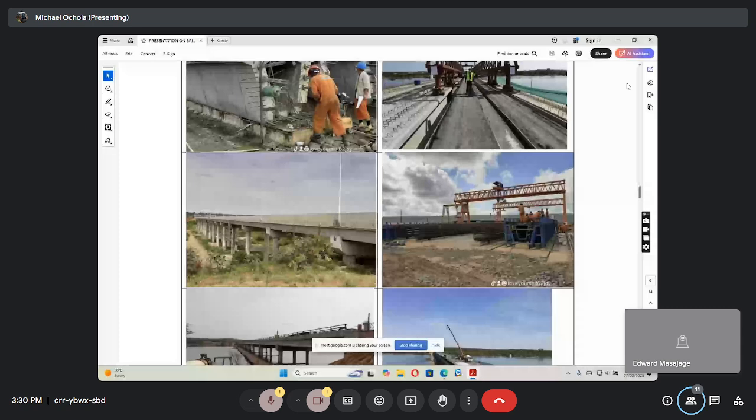So that is that. And then for maintenance, I've told you already. What you construct must last for over 100 years. But how do you ensure it? That's when you do regular inspections required to identify any defect arising, so that you are not waiting 10 years to check, when the crack has really started to grow and it becomes expensive to arrest.